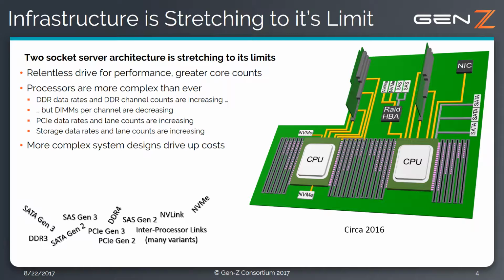Now, in circa 2016, the CPUs expanded to 6 DDR memory channels per CPU socket and added additional PCI links, lanes, widths, and slot count. CPUs also integrated SATA links to support low-end storage requirements. DDR Gen 4 was now prevalent, and additional interconnects, such as GPU-specific NVLink technology, emerged. Another technology that emerged in this time frame was NVMe, which allows solid-state disks, or SSDs, to be accessed directly over PCI without conversion to SAS or SATA protocols.